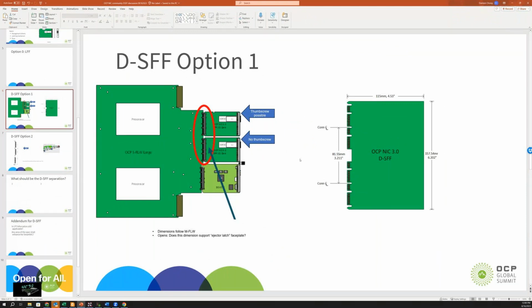Yeah, I agree with you, and I'd further say I'm not even sure we can solve the PCIe signal integrity problem. I was being generous, yeah. The things we want to do with the board area include DDR and more high-speed Ethernet lanes. Neither of those really traverse a board-to-board connector very well. Even if I can put my VRs or something on the other one, I still have losses and voltage margining that I would eat into. So there are very few things I can put on the other board to really help.